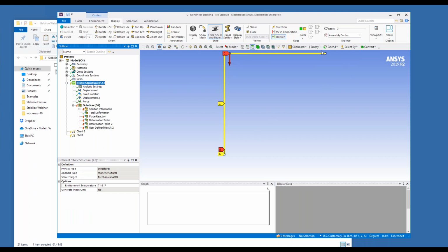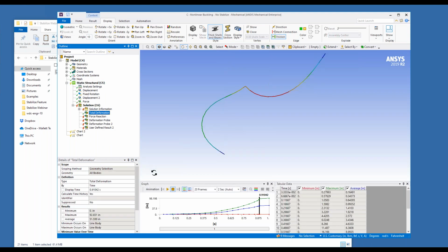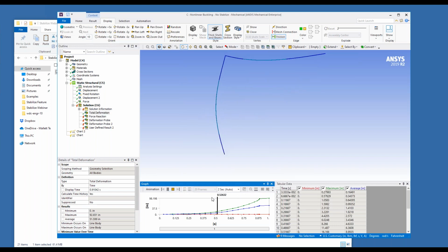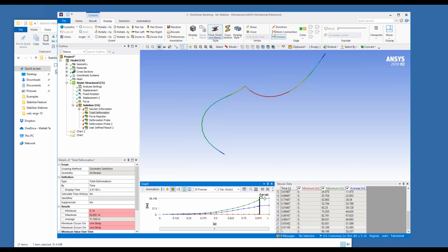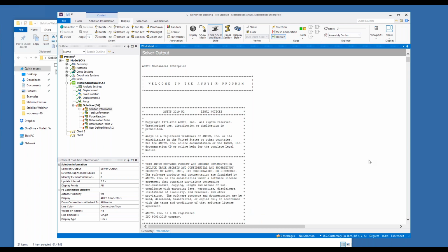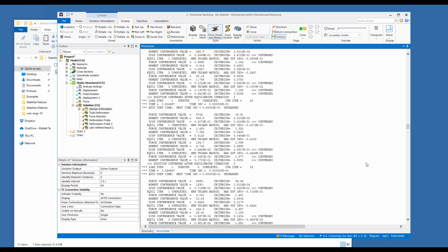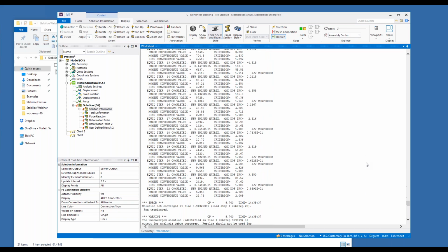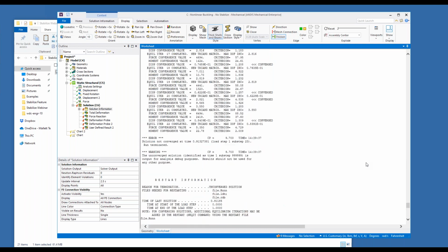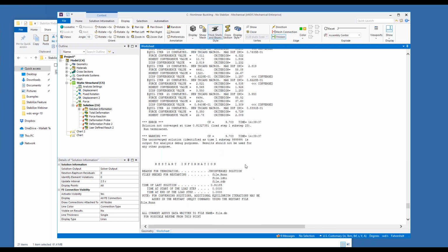This is the application, and we get a frame, 2D, apply a load here, increase the load, at some point the solver just stops. And you can see it here if you animate that. See this? That's it. Stops here exactly at this point. Stop, stop, stop. And beyond that, then it goes nonlinear. And what happens? You go back and look at the output file, and you'll see the forces. I'm going to go fast here just to show you that it did not converge.